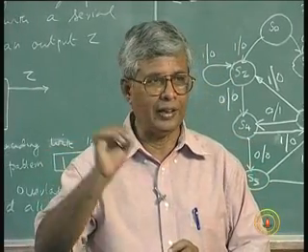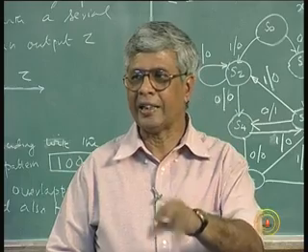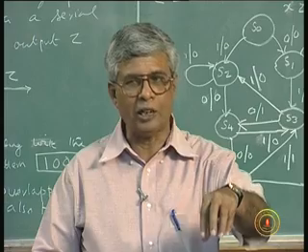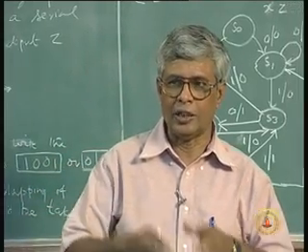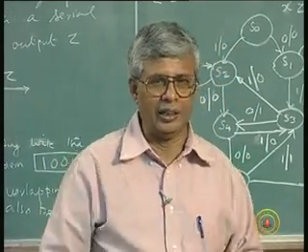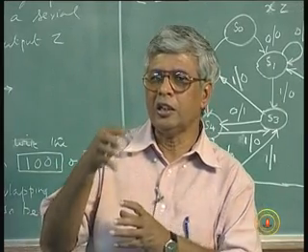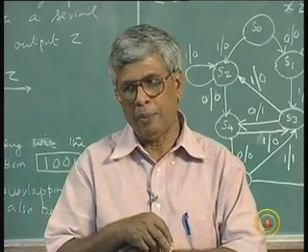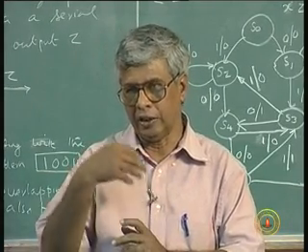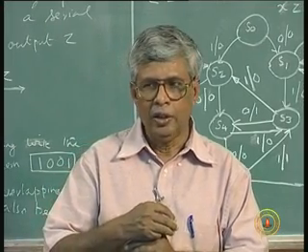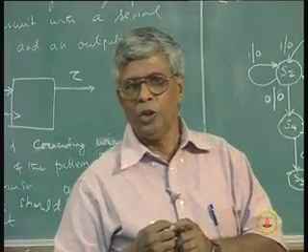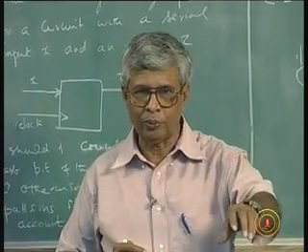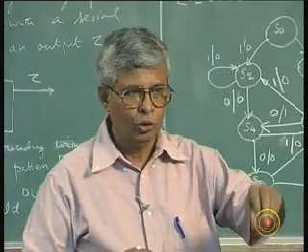I reduced one NAND gate. Today, these ICs, integrated circuits, have a large number of gates inside. On one single chip I can have gate-equivalent functions. Even though we call it a 1000 gates IC, it does not mean that 1000 gates are physically sitting there. There are functional blocks within that IC which are capable of delivering the performance of about 1000 gates. So what is the point in having performance like that, and then reducing it from 767 to 734?